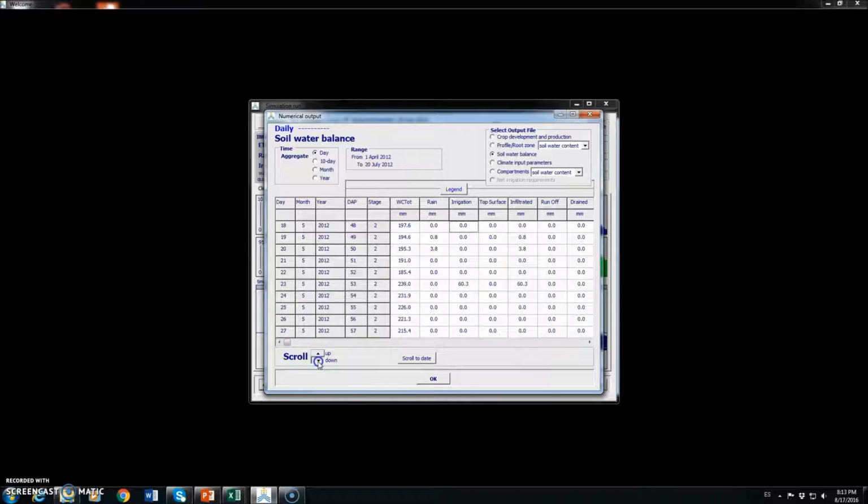If we go down, we will see that the next is June the 1st, and then June the 13th, and then June the 23rd, and then July the 3rd, and we would have this final irrigation on July the 16th that we have already discussed should be omitted. For simplicity, we're gonna assume that all irrigations have a mean net application of 61 millimeters.